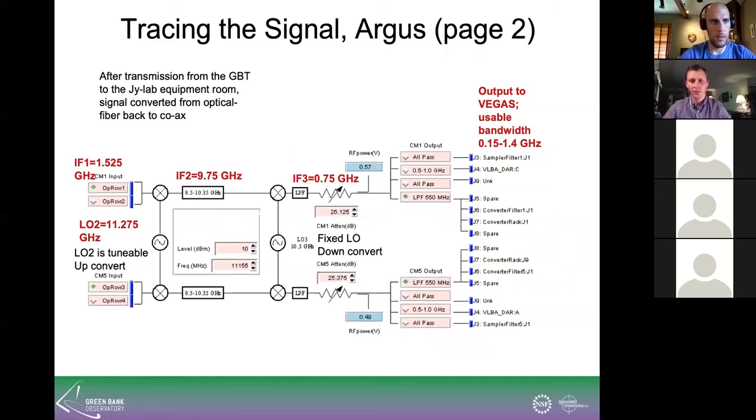You wouldn't necessarily have to do that, but for other frequencies and bandwidths there are advantages. We do this double mixing where you mix it up and then mix it down, and then you can basically throw away the frequencies either on the high side of your targeted bandpass or your low side. So that's the technique we use: even if the receiver itself didn't filter out the image sideband, this double mixing technique would.